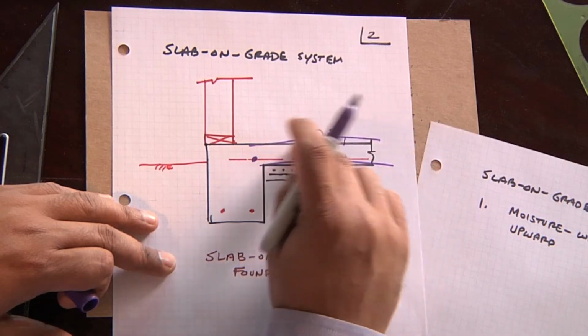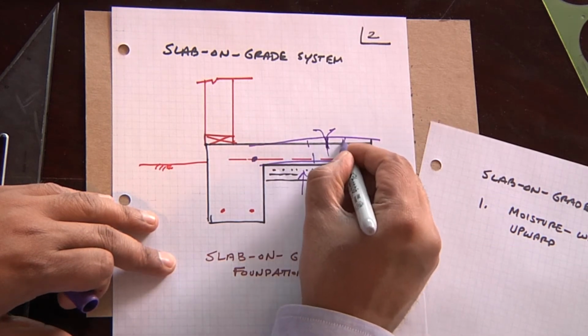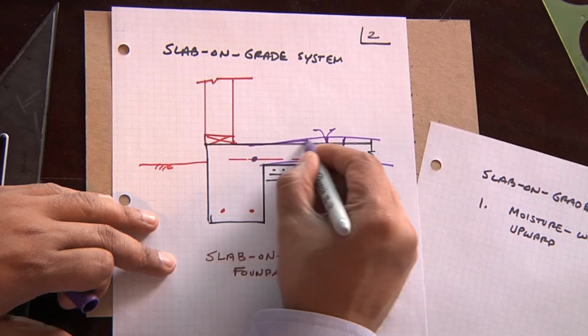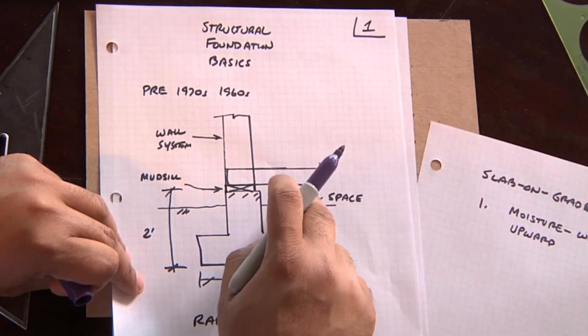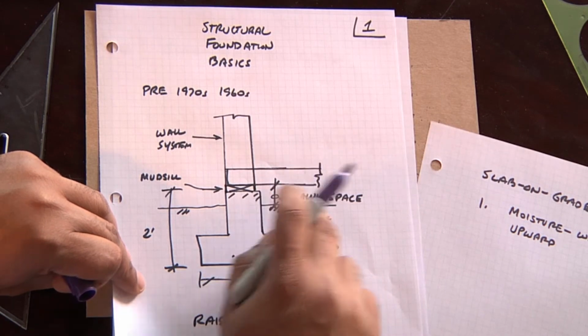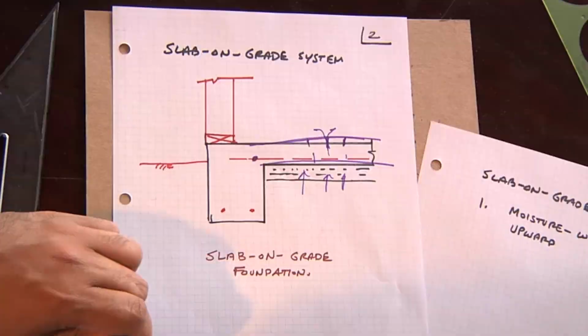This has happened on thousands of homes. I've done so many inspections in this category. What usually is involved is you have to come in here and fix these cracks. It causes all kinds of leveling issues. This kind of problem is very difficult to happen in a crawl space zone because you have this gap, and so slab-on-grades are very susceptible to that problem.